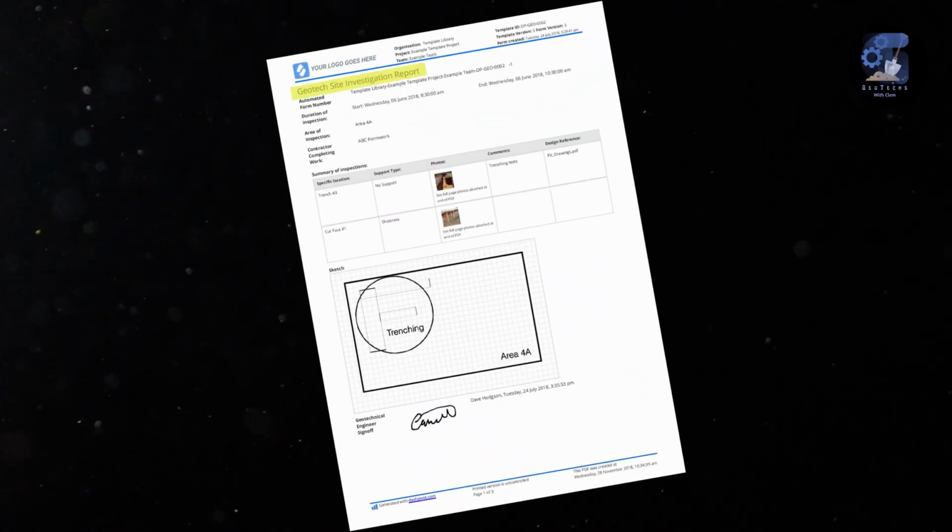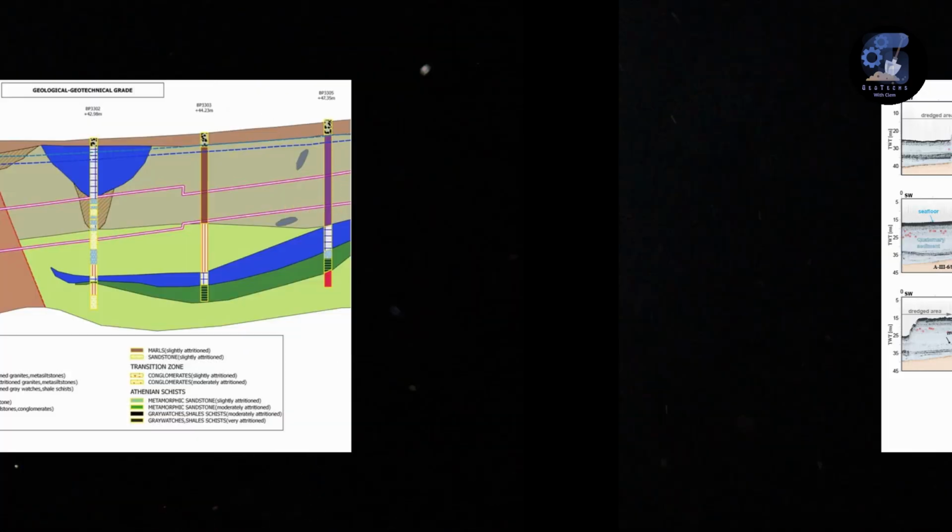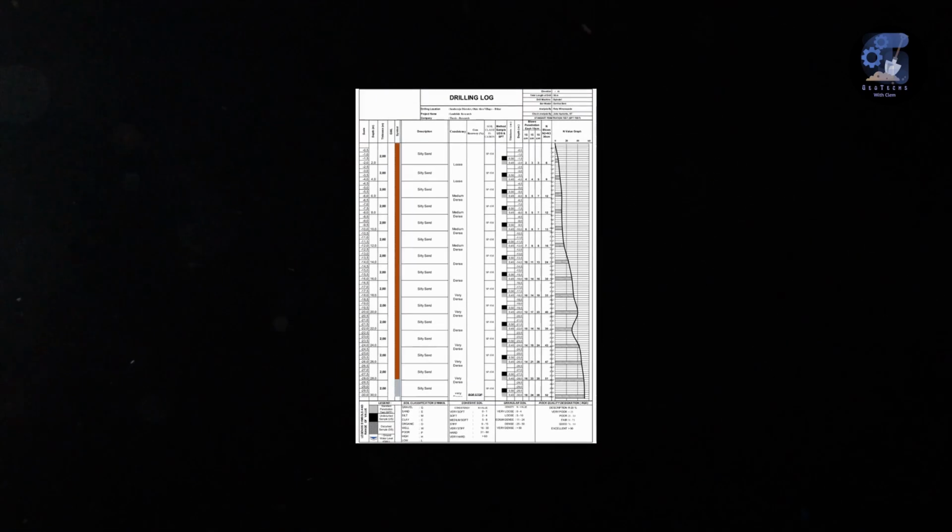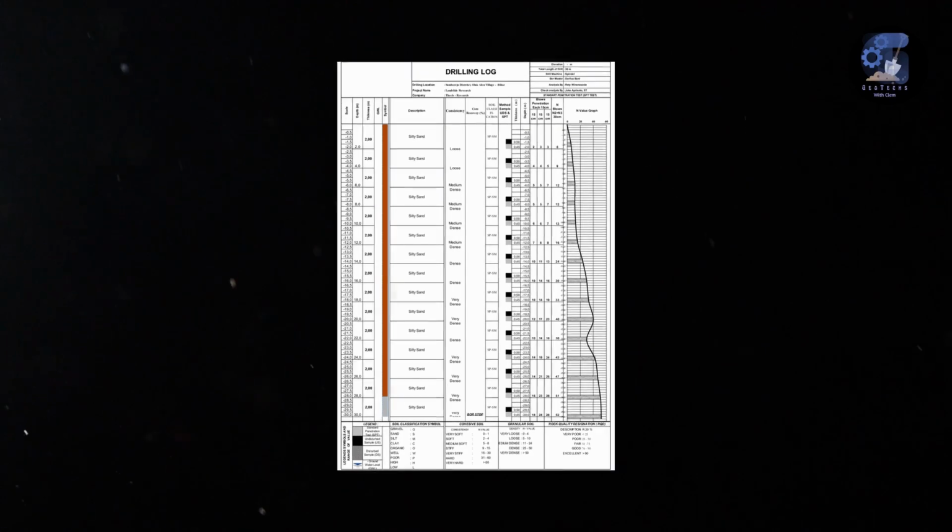To begin with, the foundation of the dam should be relatively free of major faults and shear zones. Foundations with too many defects require expensive foundation treatment programs, which increases the project cost. A geologic investigation is required to determine the general suitability of the site and to identify the types and structures of the materials to be encountered. A handful of ground parameters have to be determined and recorded in a site investigation report.